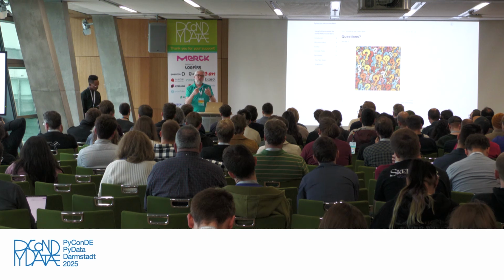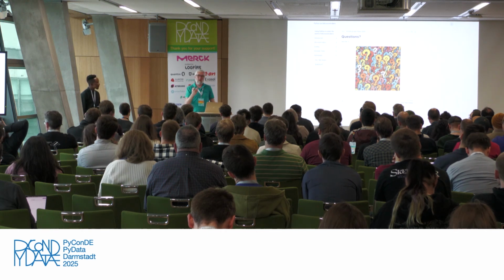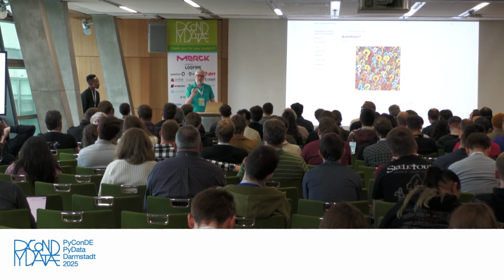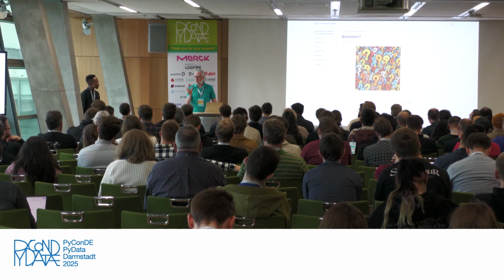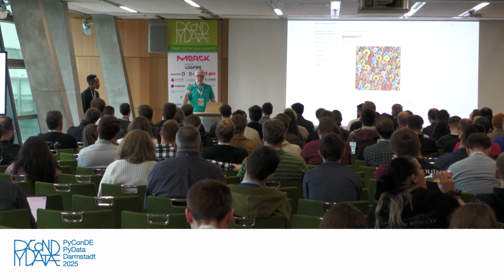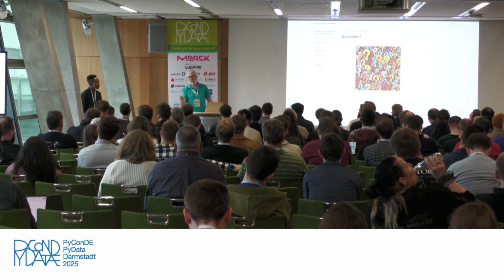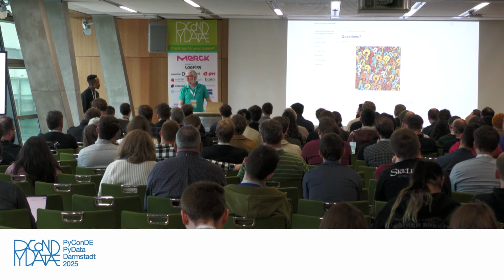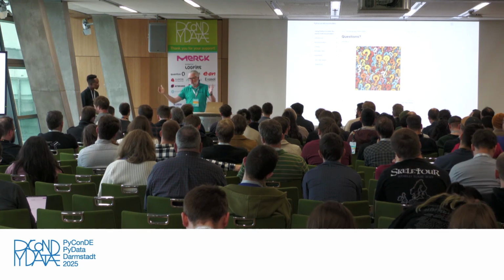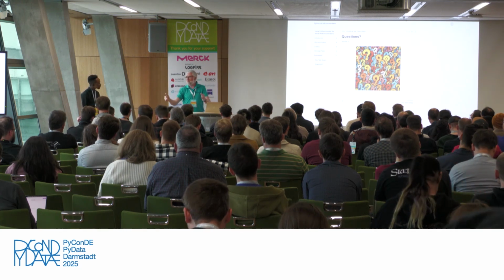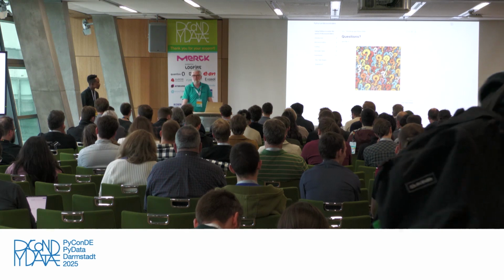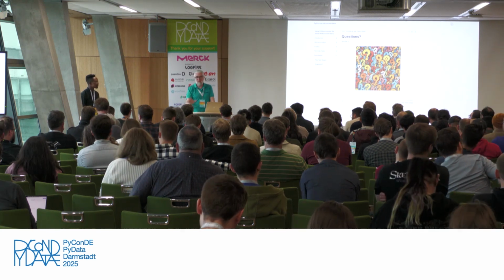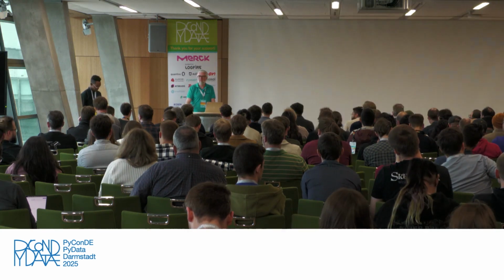And on the microcontroller, it's funnily the opposite. It's the better idea to generate the list of numbers and iterate on them, because this is faster, and faster in that case can be more efficient. So if you have room for storing all your numbers, do it and just call them. Range works, but list(range) would be the better idea.